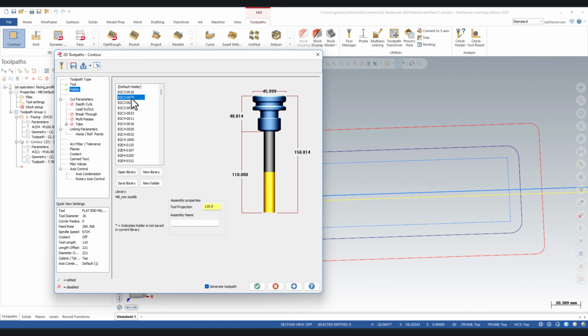It was for demand, so I am just going with 90 mm as overall length for a factor of safety, considering things like fixed clamp. So I have just gone with 90 mm. So the 50 mm will be going and doing this detailed machining.